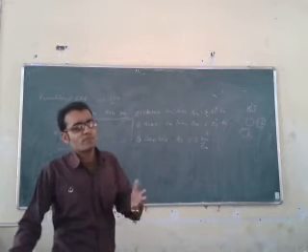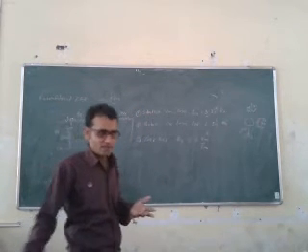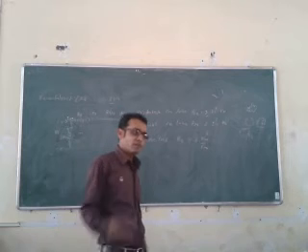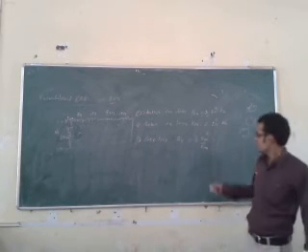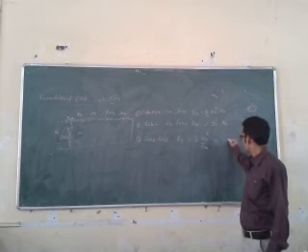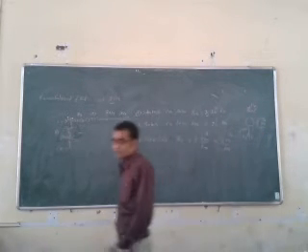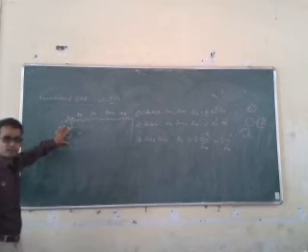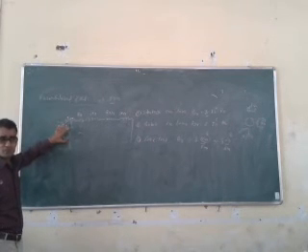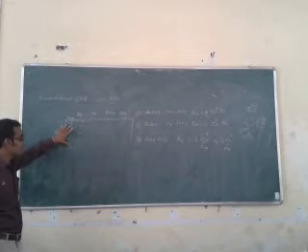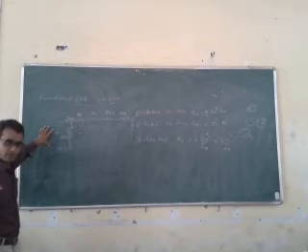So we are doing Vm square by R, or you can do I square R, not an issue. And if you convert I into V, then V by R. So Vm square by Rm is equal to, you can also write not Vm but Vs square by R. This Vm is the voltage on the Xm, the magnetizing reactance. This value of voltage is similar to the value of the supply that we are assuming.